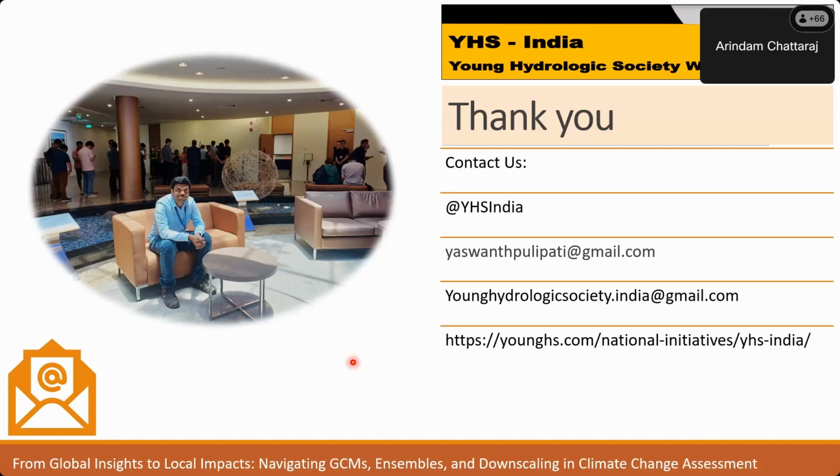Here, for your first question, when it comes to the downscaling of observations itself, for example, the IMD 0.25 degree is the most used data set, but actually the development of the IMD 0.25 degree data is again dependent on the density of the stations that they have considered. So in certain regions, the density of the stations is very less. Typically, from my experience, when I compare the extremes, for example, if you go to the highest rainfall that has occurred in Bombay in 2005, 950 mm, but if you see the IMD 0.25 degree data, you will not find it, because the interpolation will smooth out such values and you may see lower values. So even if you're trying to downscale the IMD data again to a higher resolution, you need to have a proper independent variable so that the values will be properly downscaled to the higher resolution with magnitudes of such high rainfall. Or else there is no use of again bringing down the IMD data to a higher resolution. So we should keep that in mind.